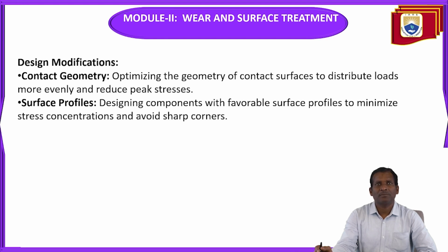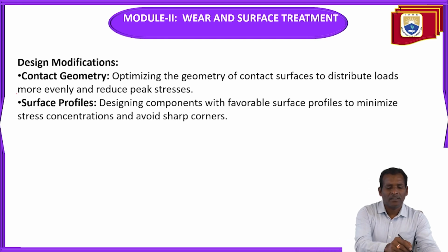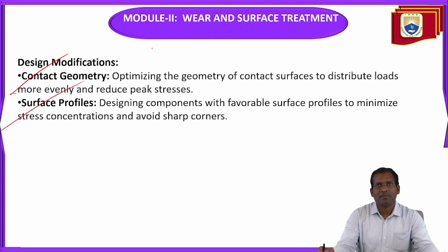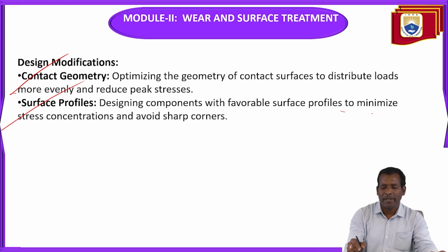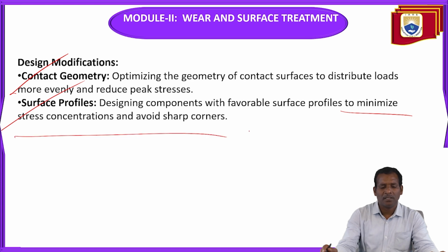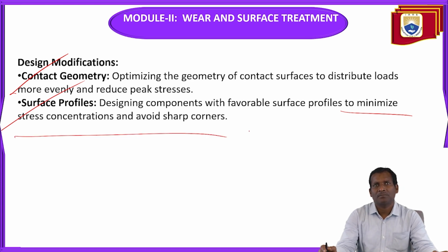Design modifications: contact geometry and surface profiles. Optimize the geometry of contact surfaces to distribute loads more evenly and reduce peak stresses. Design components with favorable surface profiles to minimize stress concentrations and avoid sharp corners. It was already seen in the previous slide.